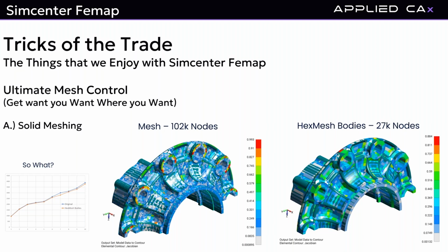If you've been reading a bit, you know a little about isoparametric theory and how it uses Gaussian integration. It's not using Simpson's rule for calculating the volume of an element; it's approximating it via Gaussian integration. A perfect element is 1 by 1 by 1, be it a tetrahedral or a hex. That way Gaussian integration does no extra work, gives a perfect calculation of volume, and you get the best stress results. If you've listened to me before, you've heard this phrase: if it looks good, it is good.